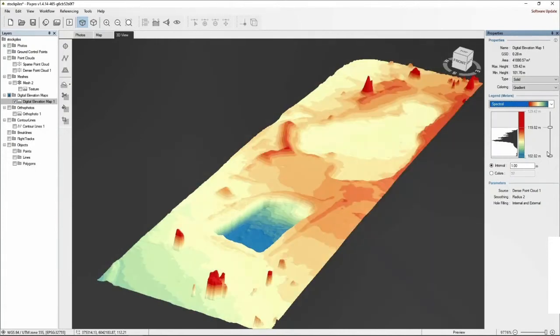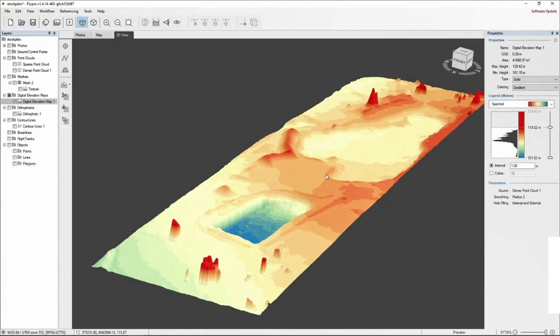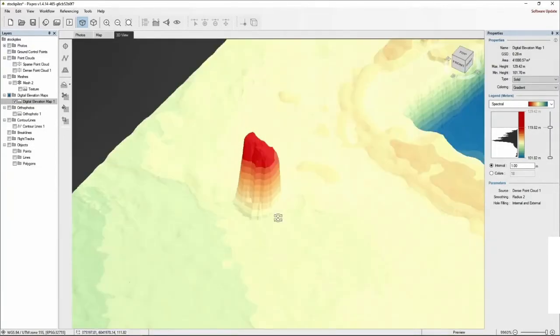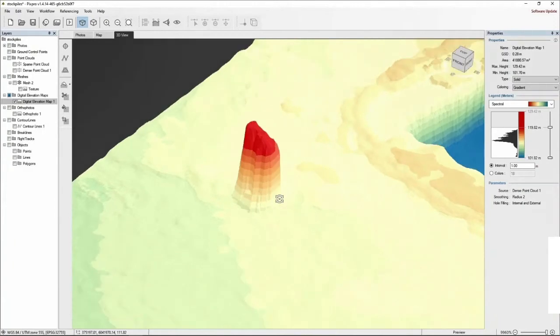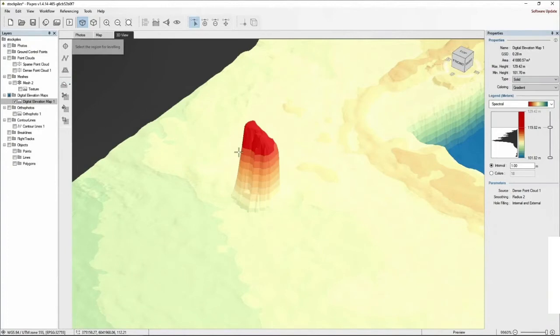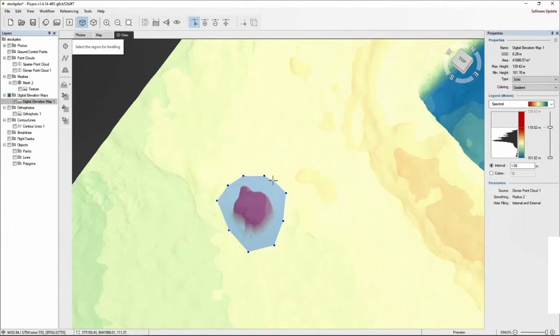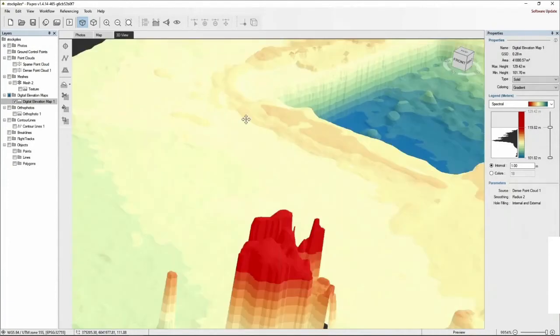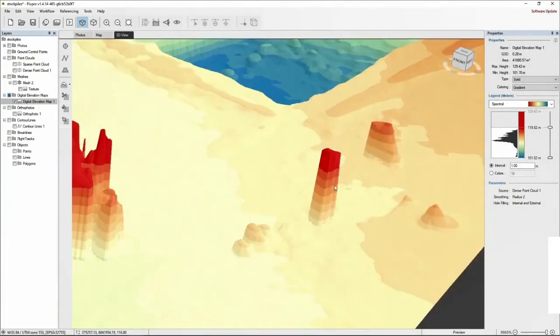Also, we can manipulate said surface. Any unwanted features that have been obtained during the photogrammetric scanning can be deleted right on the surface. Now in the video, I will use the leveling function to delete this bush, I think. There was maybe a tree or a bush that is not wanted here. It is a very simple tool based on a polygonal selection, which is drawn by the user very easily. And then just by the single click of a button, the feature is now gone from the surface.